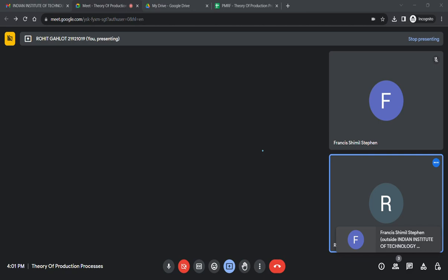I'm not saying to remember this, but with practice you will remember this, because in all the problems it is the same. In the second, third, and fourth problems I will solve this. I just wanted to end this problem quickly. So for the cylinder, the V by A will be D by 6 for a side riser whose h is equal to d; you can put the diameter directly.